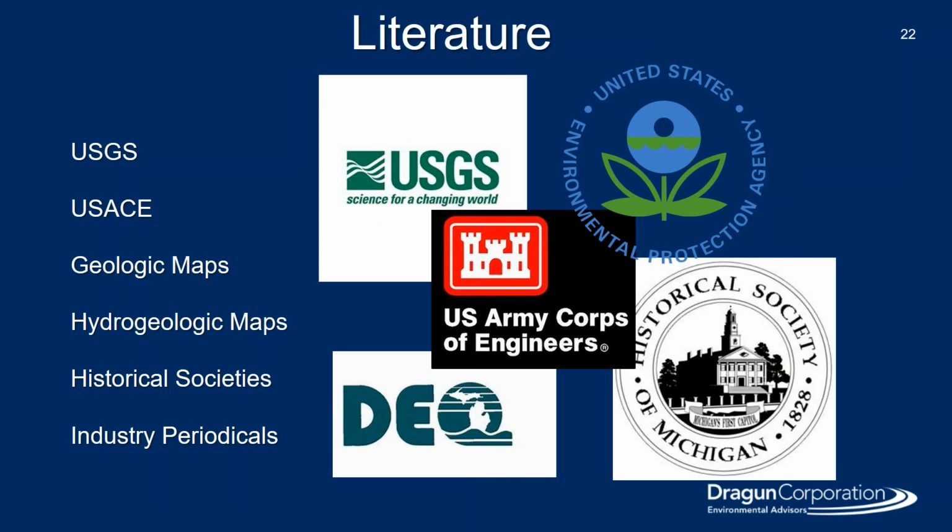And when it comes to trying to find out a variety of, I'll just call it technical things about your site, there's a lot of available information in the literature. You can have a pretty good idea of what you will be drilling into geologically before you ever put a hole in the ground, just by doing a little bit of homework. You can know by looking at a number of sources if you'll encounter groundwater, for example, or if you're likely to encounter groundwater. And a lot of this has been bought and paid for by our tax dollars. So certainly use it and use it to your advantage.